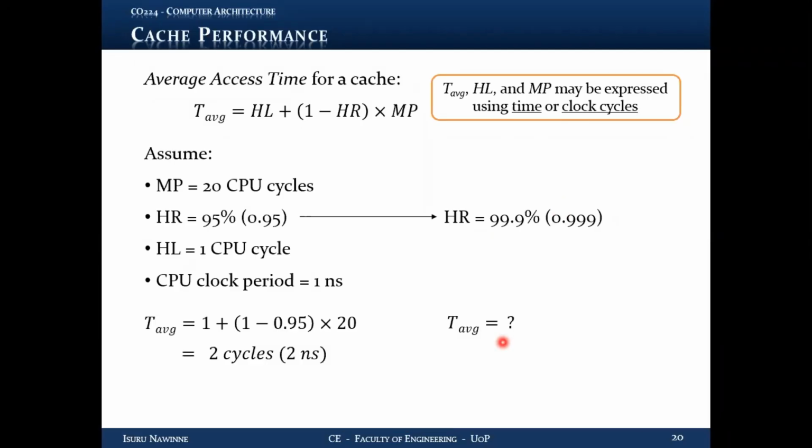So I have one answer sent to me privately. You can reply to everyone so everyone can see. It's 1.02 nanoseconds. Yes, 1.02 nanoseconds. So you only have to replace this hit rate 0.95 with 0.99, and everything else is the same. So you end up with 1.02 clock cycles, 1 nanosecond, closer to 1 nanosecond, right?